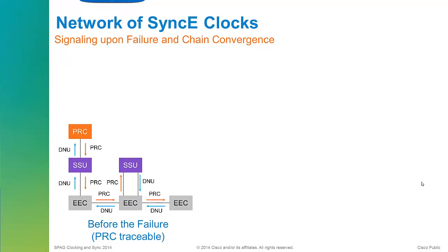Normally what used to happen was every Ethernet circuit would just negotiate a master and slave between each end, like a transmit and receive slave, and it would then just use the frequency of the master on the slave. So every circuit could be running plus or minus the frequency. What SyncE did was change the router so that the frequency that's used as a source is then used as a frequency source for all transmission from that box. So we'll cover this a little bit more later, but in general, just get the idea that there are no packets in Synchronous Ethernet.